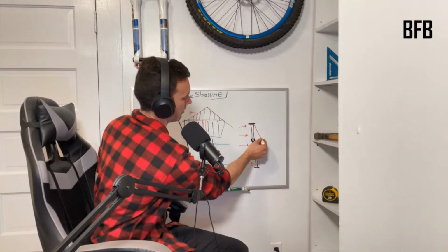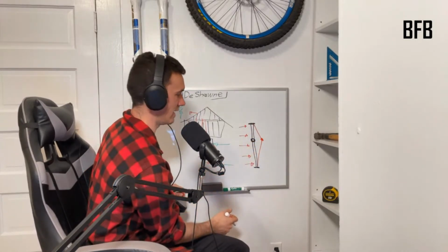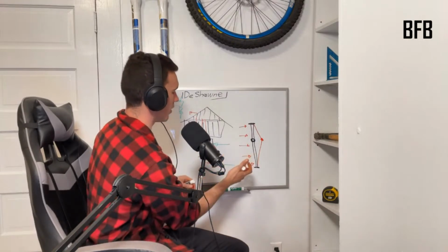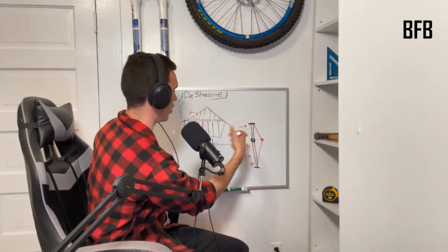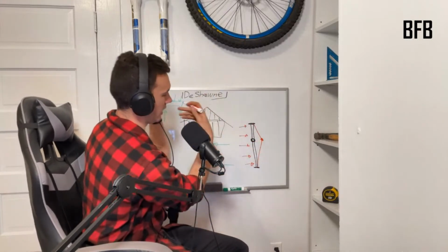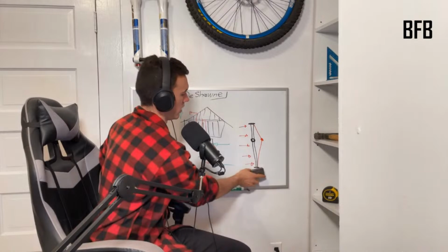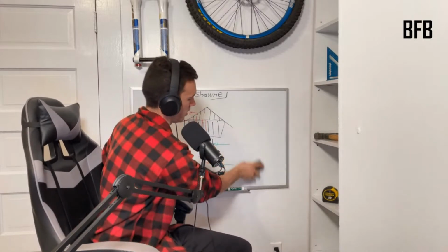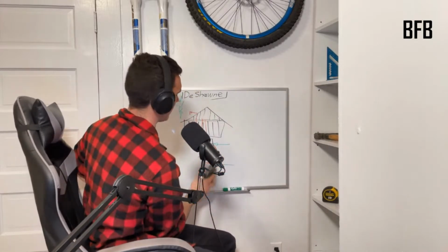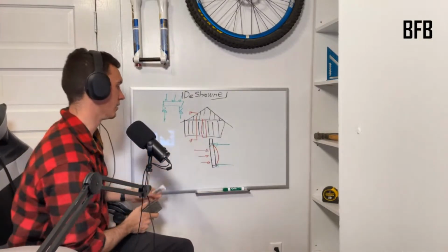You'd get a hinge problem. This would buckle in right here and you would have a very bad day. Likely what would happen is, if there was no wood supporting this, you'd get a bunch of sheetrock busting and cracking and blowing in. Now, this is like a crazy wind event, right? So, you got other things to worry about. But that's a possibility. That could happen. It could happen to you. So the ceiling diaphragm is the thing that keeps that buckling in from happening. It's this top force here.